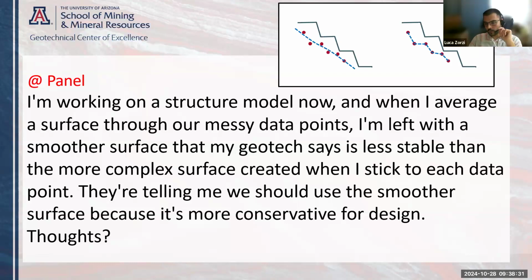Yeah, with the volume, it's very tricky sometimes because the assumption ties up with what Ian was saying earlier about how you leave a model to a client and then they come back 2 years after and then they assume, right? So the risk is that if it's not communicated properly, then that volume is considered to be a full gouge of X amount of centimeters or meters, whereas in reality, you're just defining a zone that has some degrees of interconnectivity or some percentages of rock bridges that may actually not be an issue for stability, or can be a complete issue for the stability of the open pit. So even with the volume, it can get tricky if it's not communicated properly.